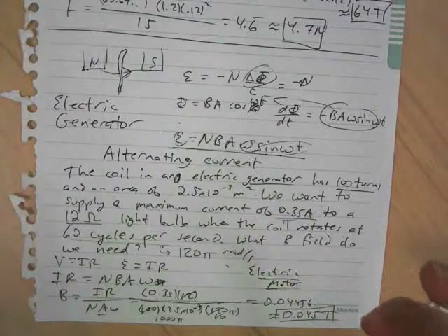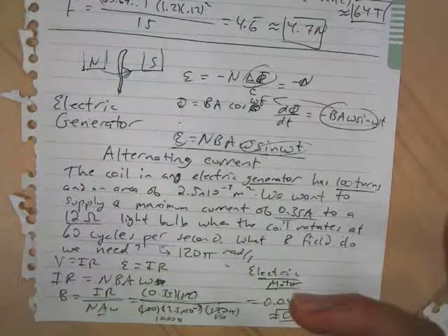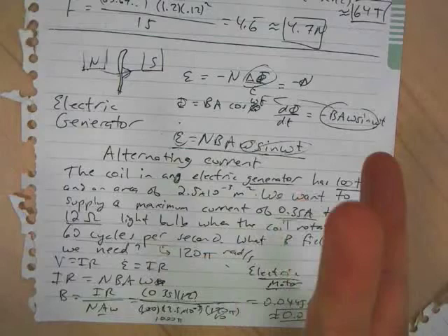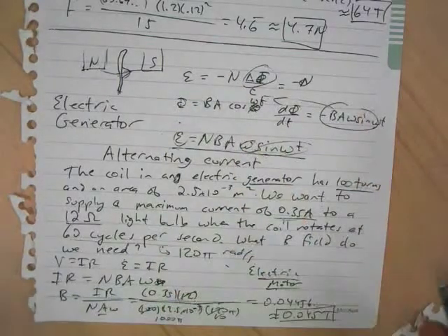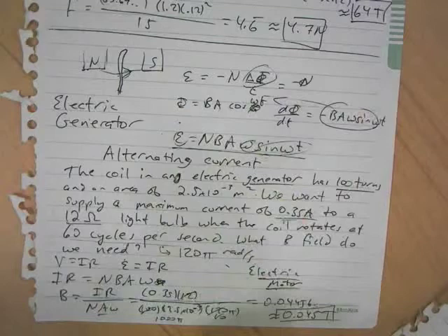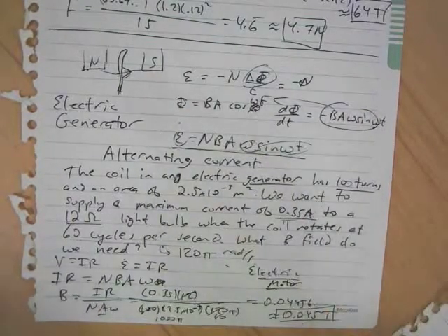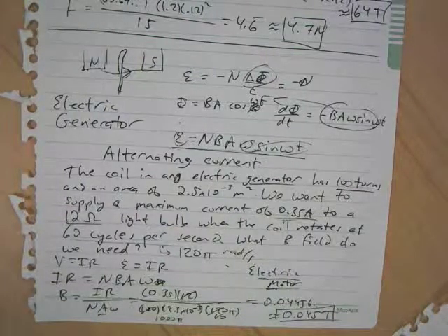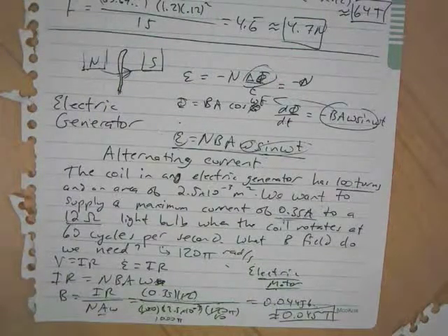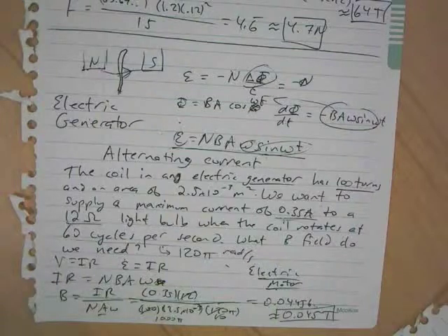And then the rotation, as the loop is torqued around, the torque would reverse as the coil rotates around. However, there's an alternating current fed into the loop that is synced up with the rotation of the coil, so that torque produced is always in the same direction, and so that continues to generate mechanical power from the electric power. So a motor is kind of the reverse of a generator, which makes for a kind of interesting application.